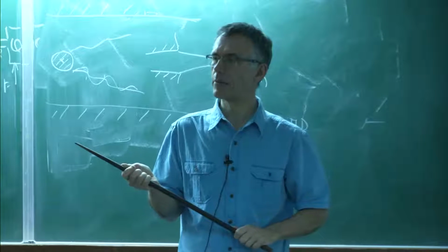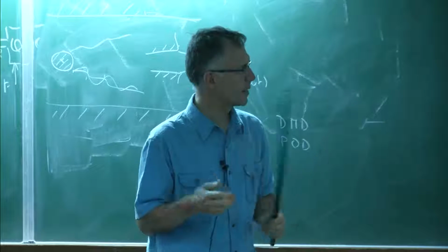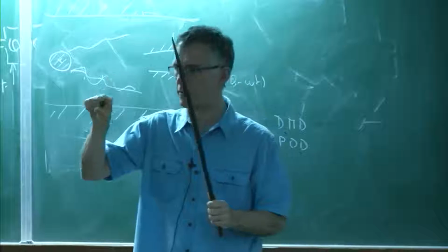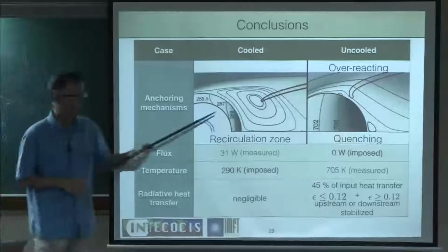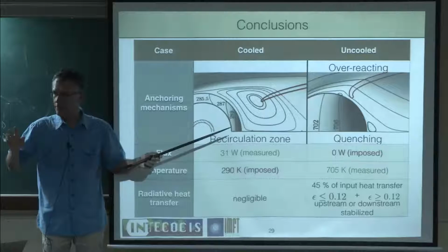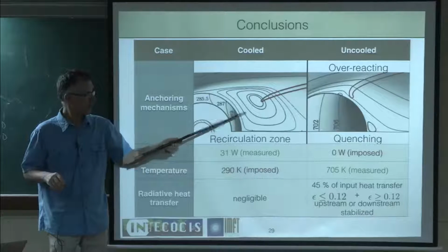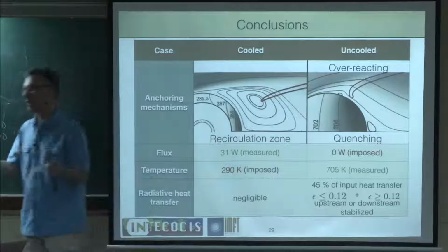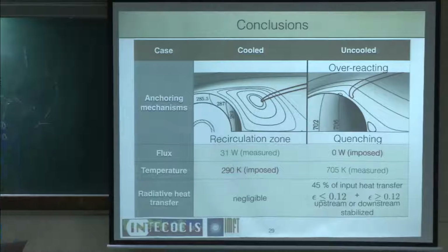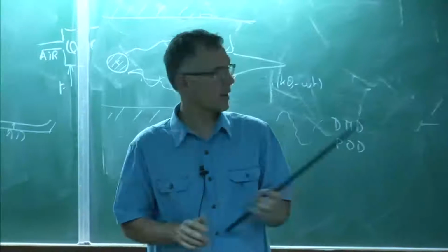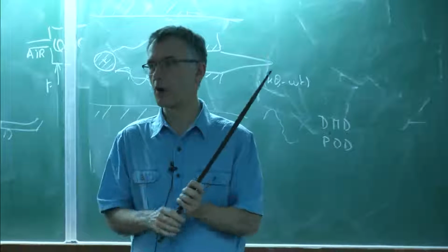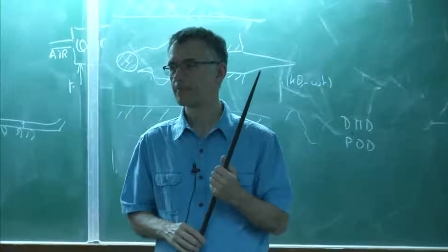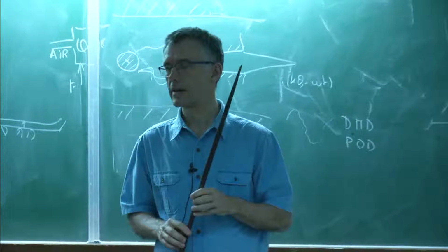That's the MIT paper, you mean? Yeah. The MIT one was on a square flame holder, which is a little bit more complicated than that one. But clearly, whatever you have, if you change the flame position, the flame transfer function will change, and the instability will be different. That's clear. Except that in this case, we stayed in a stable regime, so there is no problem. Yeah.